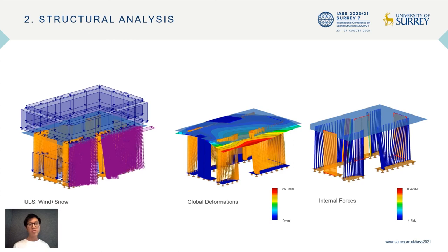This led to a redistribution of normal forces in the structure. The analysis showed that the pre-stress in the twisted elements actually disappears after a while, but has no impact on the reduction of the buckling length. A subsequent design check with respect to Eurocode 5 ensured a sufficient material safety.